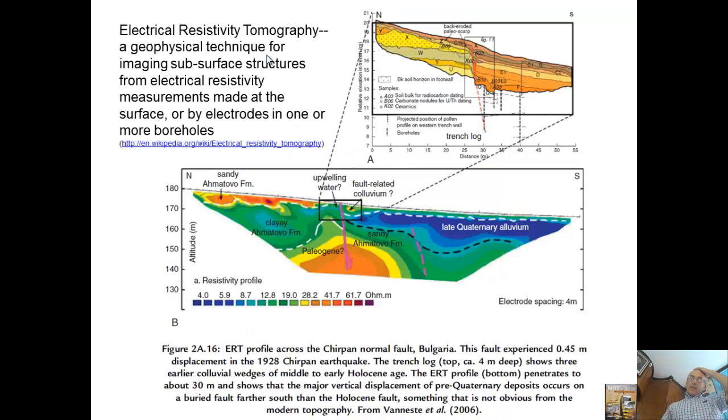So the last of the methods that they present in McAlpin is electrical approaches, so electrical resistivity tomography. And what this one does is usually there's, you may have a source, but you may not. You can use passive or active approach, but you just move over the area with an electrode, basically sensing the resistivity across the zone. And this approach tends to have a pretty hard time of identifying sharp breaks because when you invert for it, the tomography below is basically a resistivity map that they made based on their series of electrode measurements at the surface.